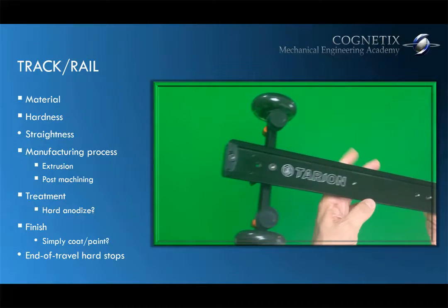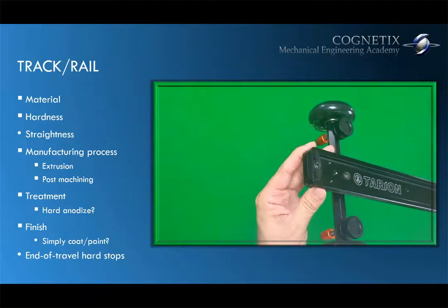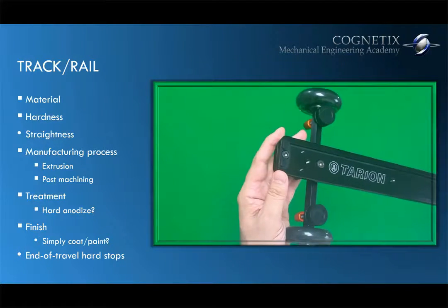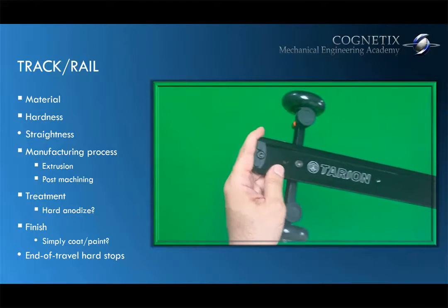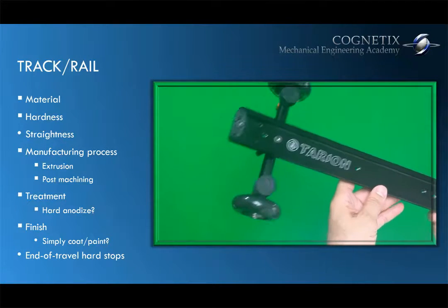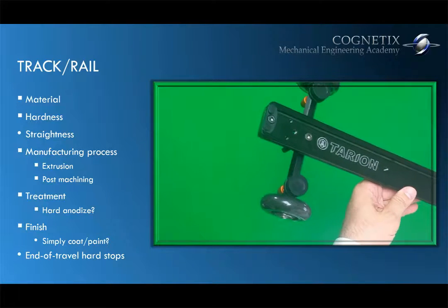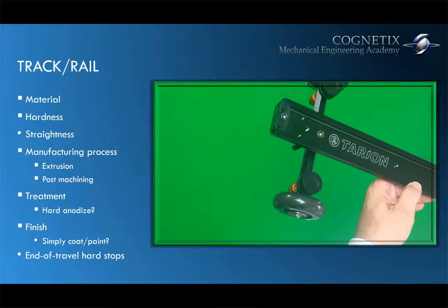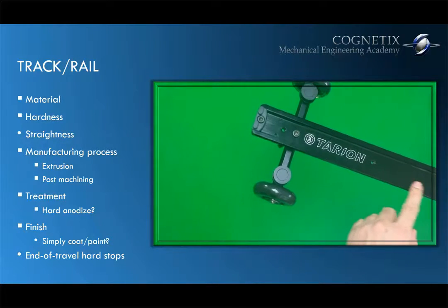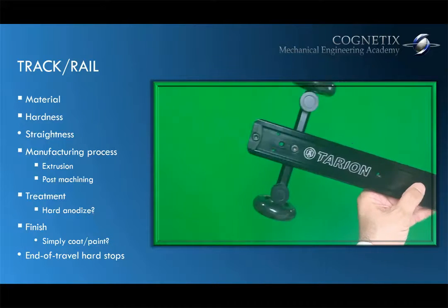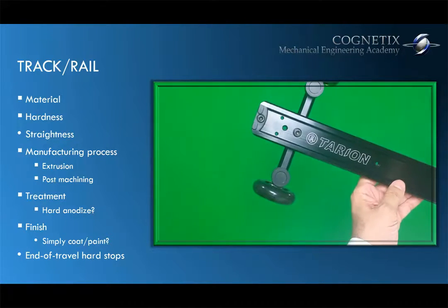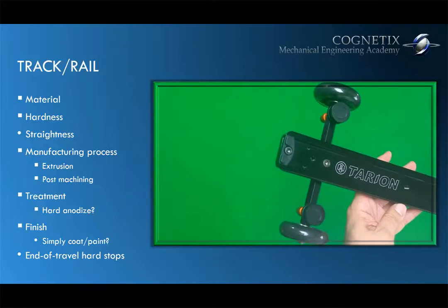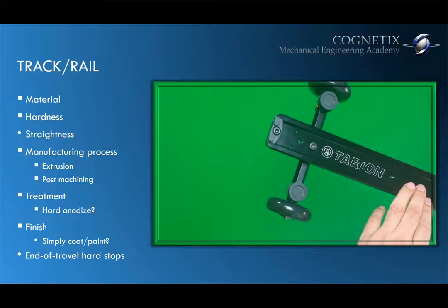As it turns out, aluminum can be anodized. It's one of the finishing processes that are an option for aluminum. One possibility, and I don't know this for a fact because I haven't looked at the engineering drawings of this product, is that they black anodized the aluminum. In the case of black anodizing, they're not painting it black. It's a different process that we also talk about in the Academy in other videos. They could have black anodized it.